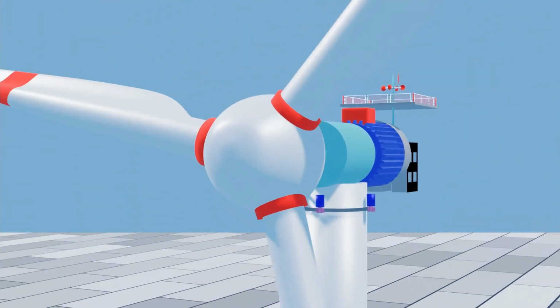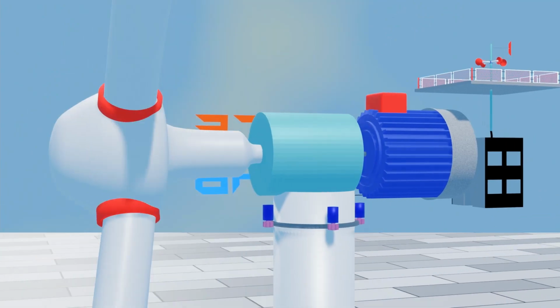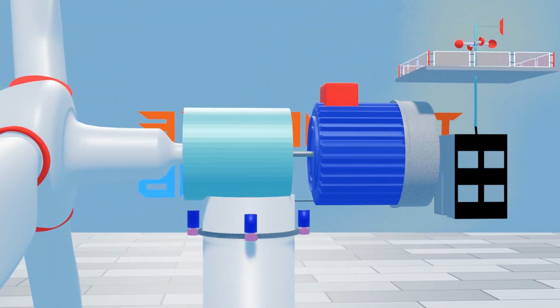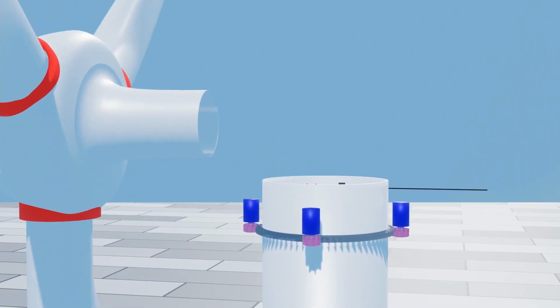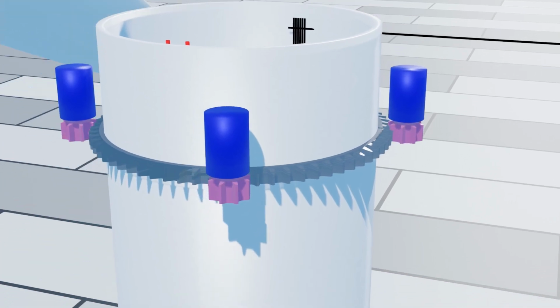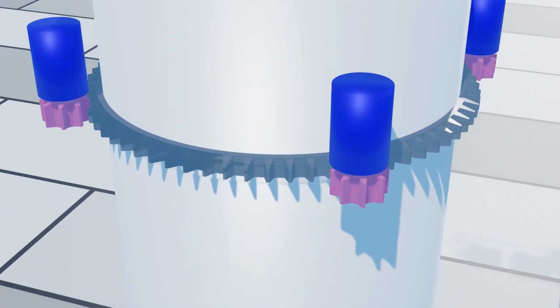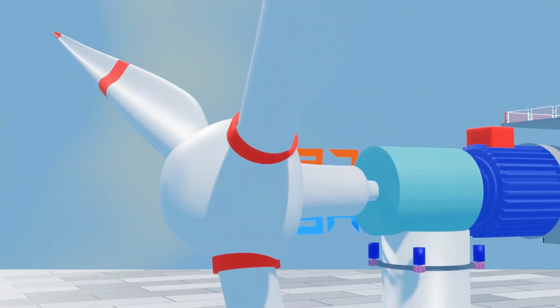Blades and other components in the wind turbine are in the nacelle. Whenever there is any change in the wind direction, the nacelle has to face the direction of the wind to extract the maximum energy from the wind. For this purpose, a yaw drive, a motor, is used to rotate the nacelle. It is controlled by the turbine controller that uses the wind vane information to sense the wind direction. A wind turbine requires a high speed of wind to generate electrical energy.